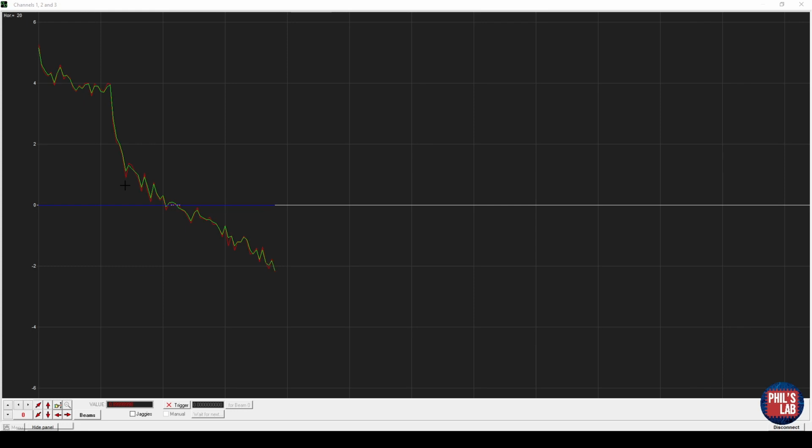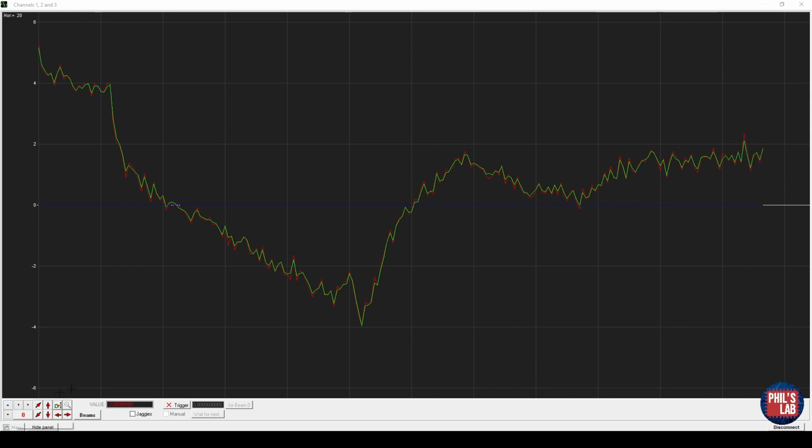Remember, we aren't applying a lot of filtering, so our filter constant is set to about 1/4. What we can already notice, I mean this is now in the units of pascals, we can see there's quite a bit of movement. I've not moved the pressure sensor one bit so far. So there'll be random walk, there'll be bias, there'll be drifting over time. So we can already see maybe pressure sensors on their own aren't the greatest thing to rely on. It also depends on what kind of accuracy we want, which we'll see later in the relative altitude measurements, because pascals initially don't tell us very much. But this is just to examine the low-pass filter.